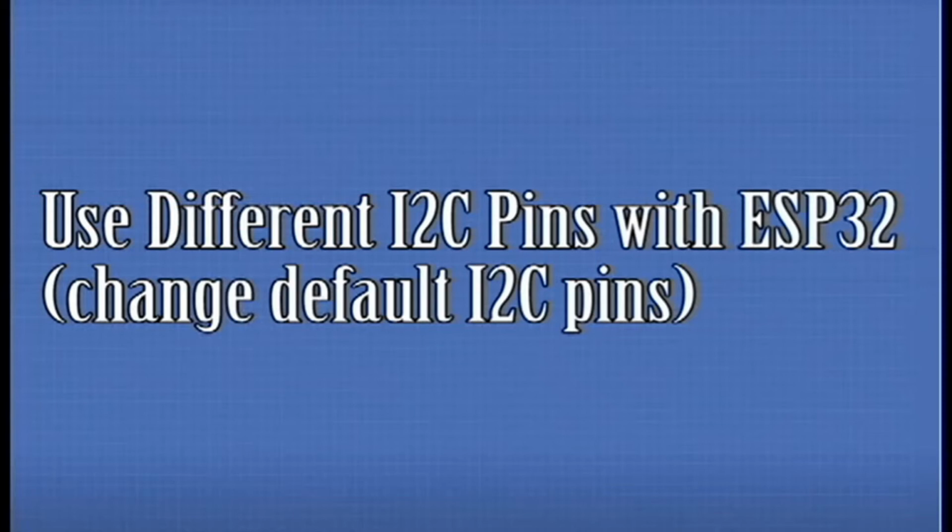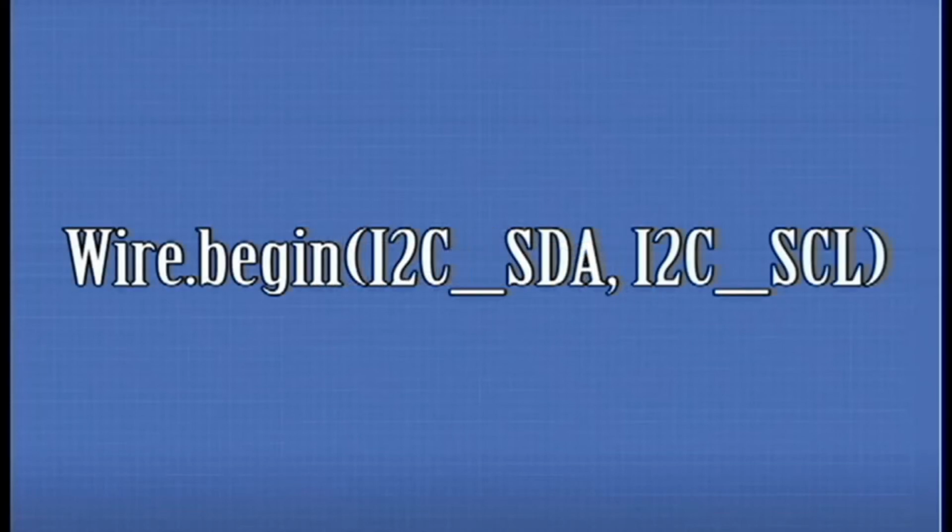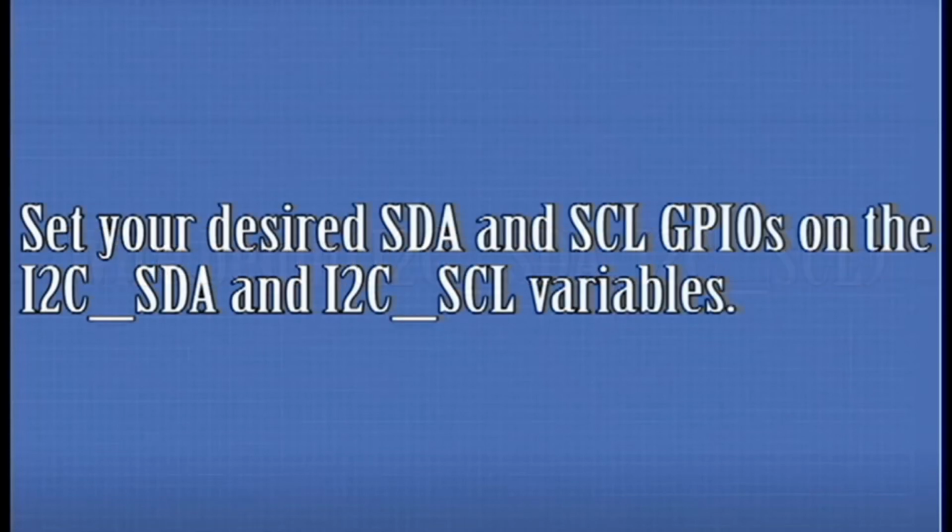Use different I2C pins with ESP32, change default I2C pins. With the ESP32 you can set almost any pin to have I2C capabilities, you just need to set that in your code. When using the ESP32 with the Arduino IDE, use the Wire.h library to communicate with devices using I2C. With this library, you initialize the I2C as follows. Wire.begin(I2C_SDA, I2C_SCL).